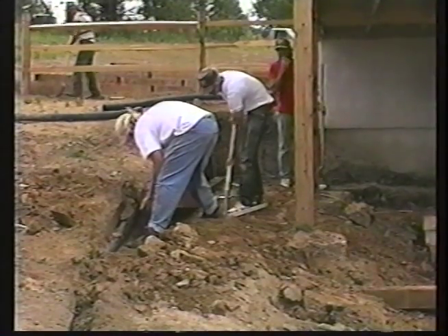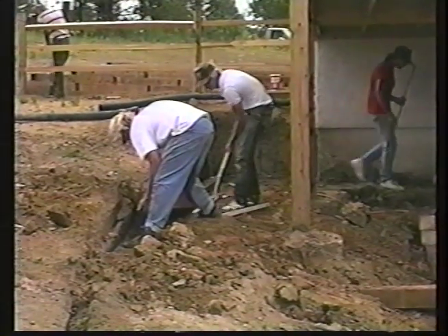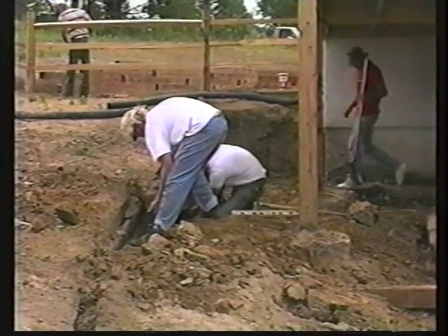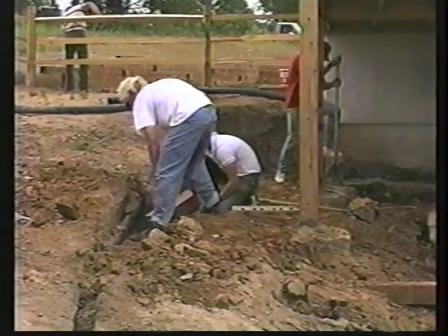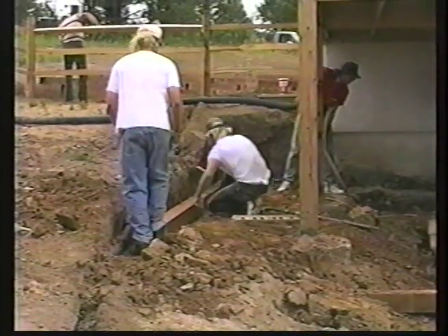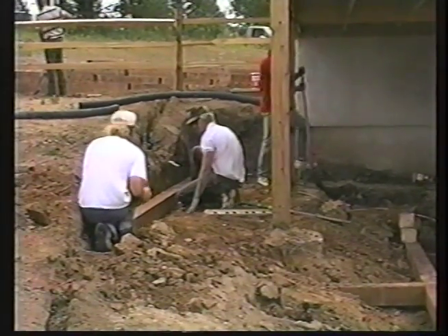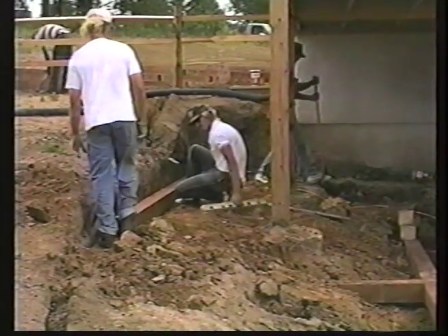Once you've located the lowest point, dig a trench about 10 feet long, 3 inches deep, and about 1 foot wide. Set the first timber in the trench and level it. Firmly compact the trench and re-level the timber. Ensure that the timber is both level and just touching the base course string line.